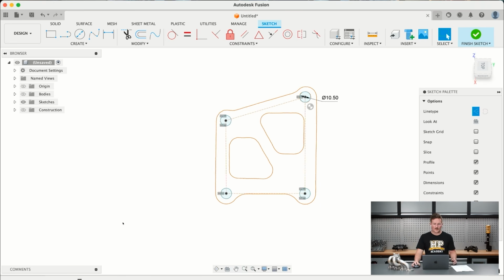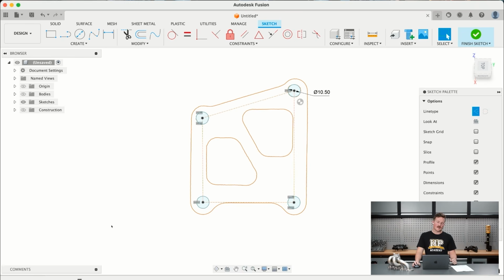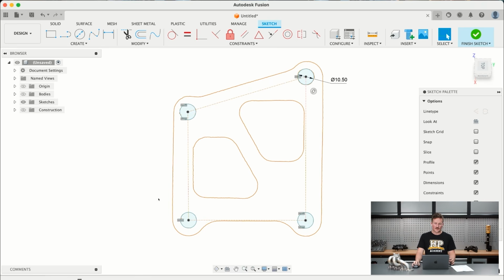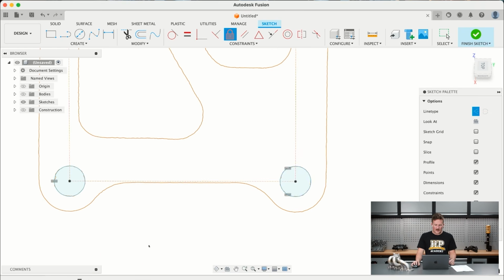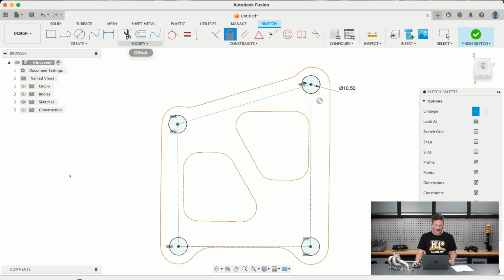And we always want the sketch to be fully defined so we don't risk losing things moving accidentally when we don't notice, and then it having a snowball effect to other issues that show up. So in this case, I could dimension these from this origin point here. What I'm going to do is lock down the position of the hole centers so I know they can't move from the positions that they're in now, because I'm pretty happy with them and their alignment to the mesh file.